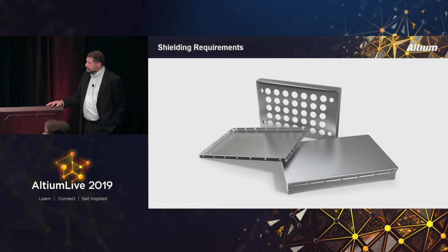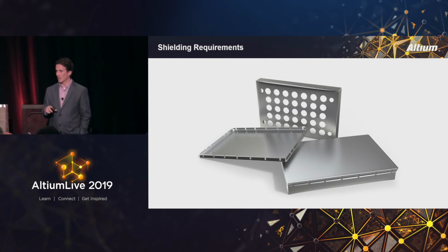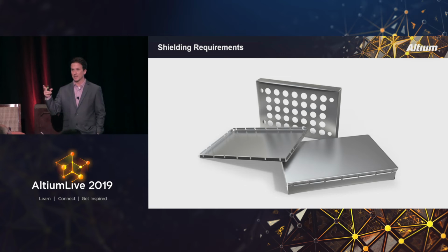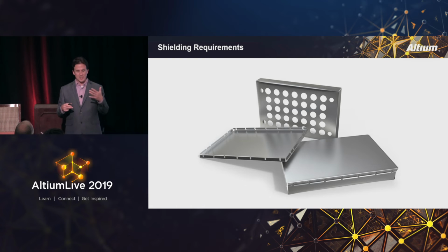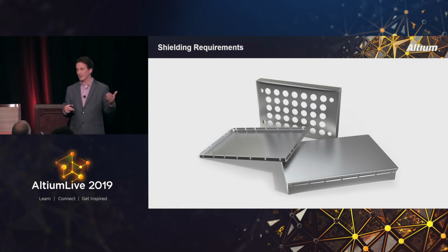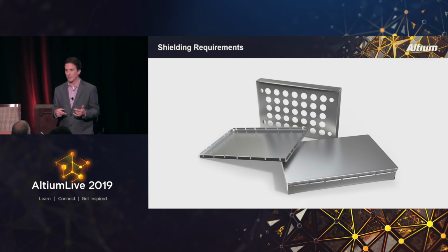One thing I'd say about shielding is you don't use a shield by just slapping it down on a circuit board. Okay, if you put a shield onto a circuit board, you need to think about filtering all the signals that come in and out of that shield and how you are protecting those signals with filters. Because if you just throw a shield down on a circuit board and don't think about that stuff, it's coming in anyways. And so now you've just bought a really expensive decoration for your printed circuit board.